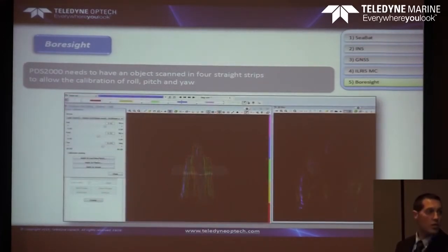align manually. So what you have is pitch, yaw, and roll. This is the order I've been told that usually operates. You have the 3D point cloud here, you can rotate, and this is a 2D view. Basically, you just move the slider, this bar, and you go to pitch, then yaw and roll, until the data set is connected together. Once it's connected, to be honest, it takes 5 or 10 minutes. It's really fast. Basically, you have a result, which are the numbers you can see here, and this is a calibration of the laser scanner and the bathymetry. So everything at that moment is completely calibrated together.